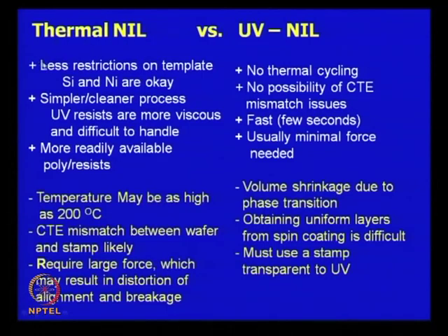In thermal NIL, there is less restriction on the template, or you can have pretty much any of the conventional materials like silicon and nickel for the template or the mold or the stamp. In contrast, in UV NIL the mold or the stamp has to be transparent to UV.